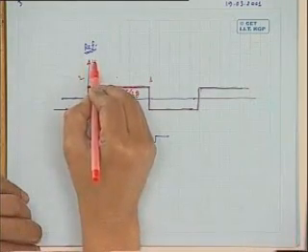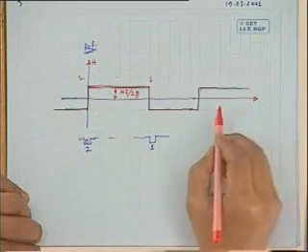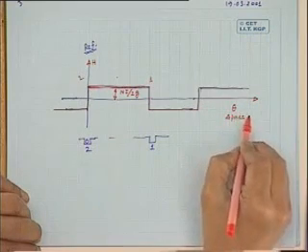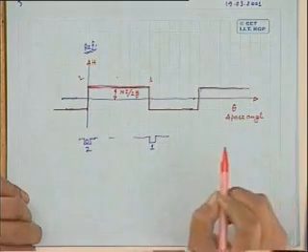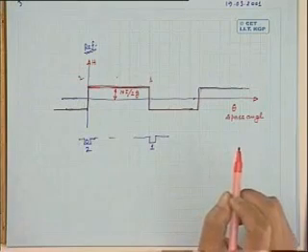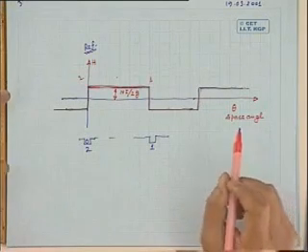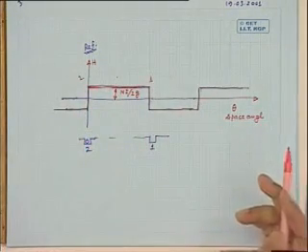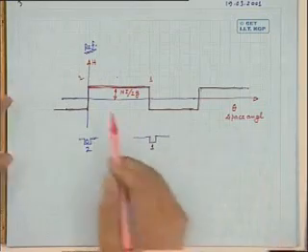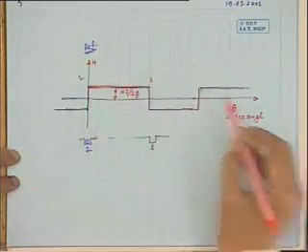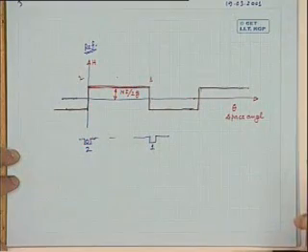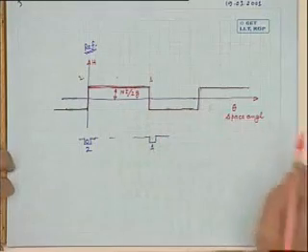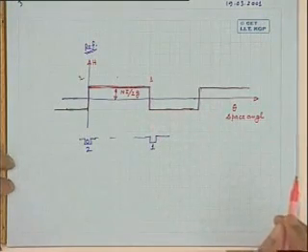So on this axis we have plotted H, and this is the angle theta, space angle, which fixes up at what point you want to know H. What will be the B distribution? You simply multiply this curve with mu 0, because in the air gap we have calculated. So if you multiply with mu 0, you will get B distribution. Okay. So B distribution becomes rectangular in nature.